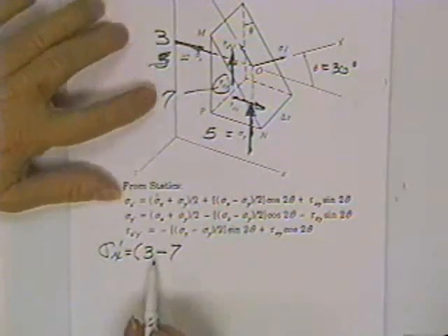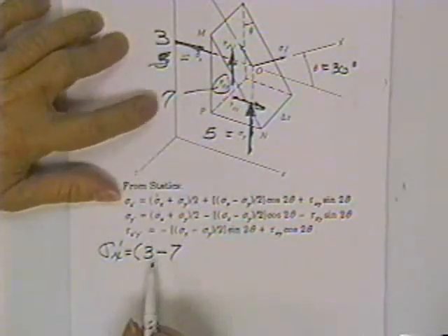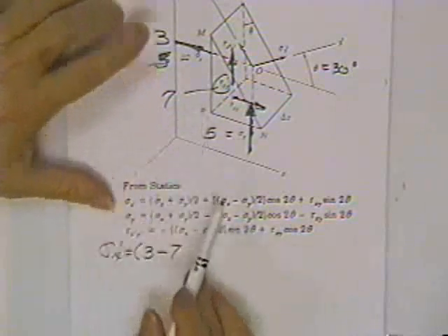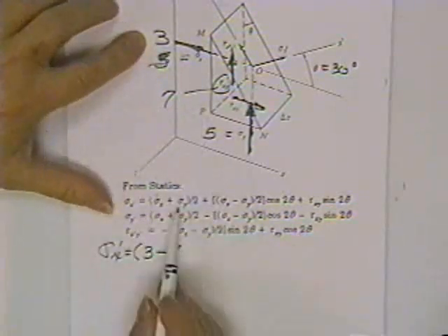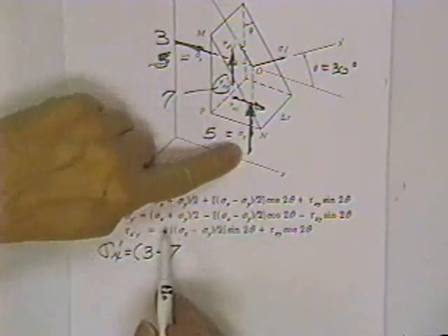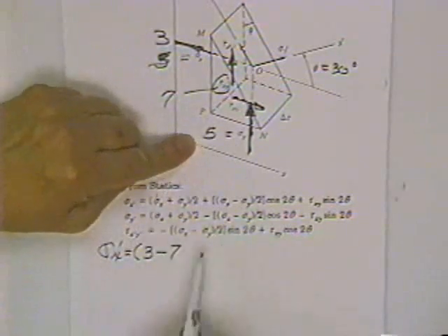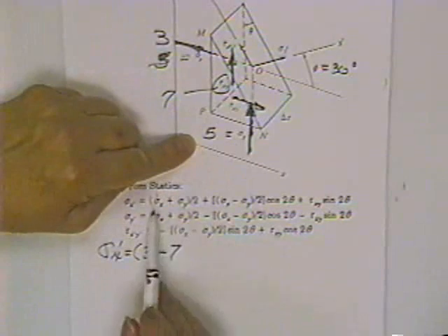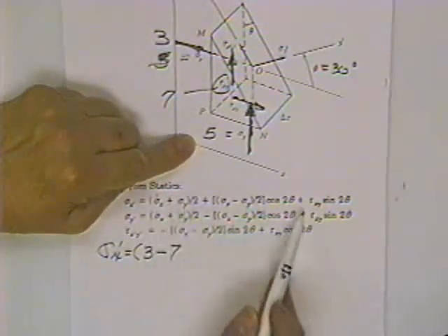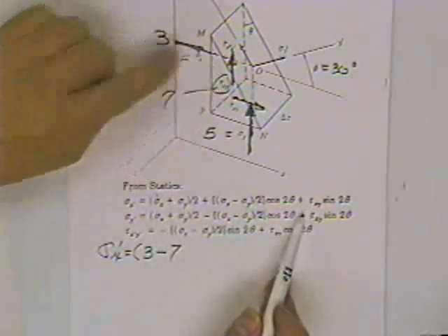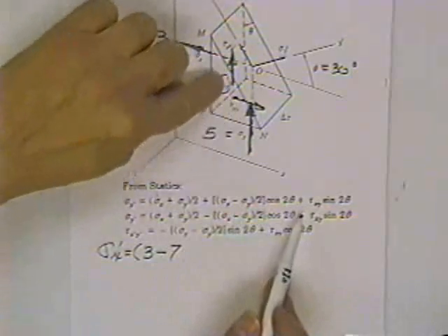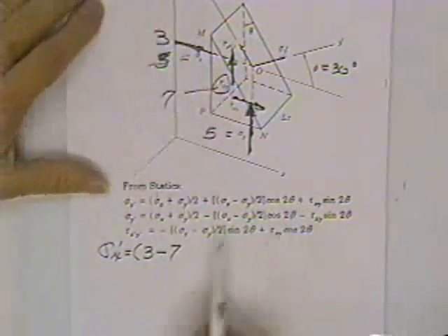The reason is because your sigma x and sigma y didn't agree with my sign convention. My sign convention for these equations is very rigidly fixed. Tension, tension, shear in the direction shown on the block. Not this way here just because it happens to be your case.